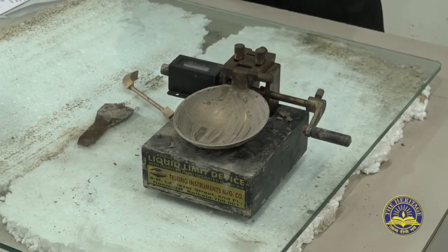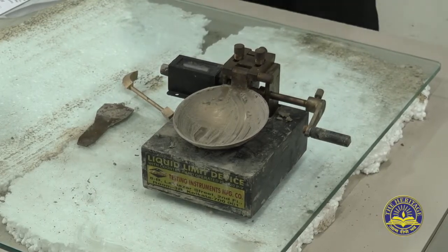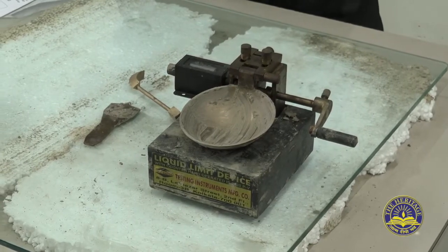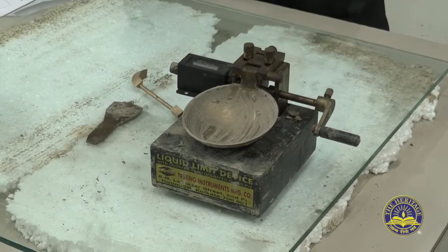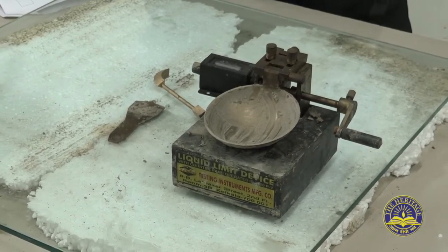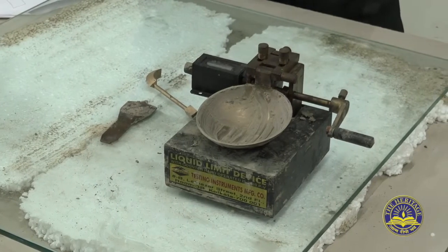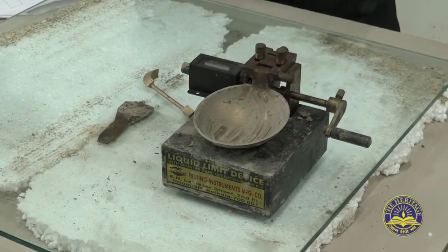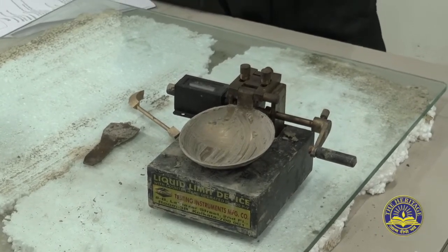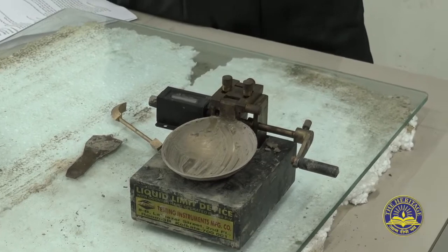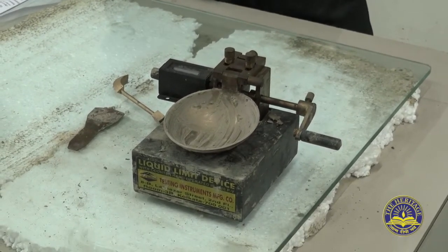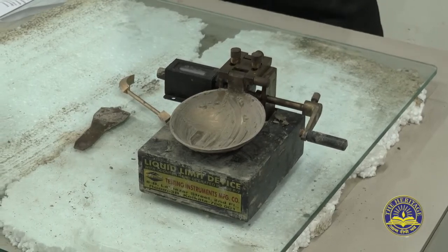And after doing all these things, you have to do a graph plotting, that is number of blows versus moisture content. Number of blows will be in the logarithmic scale, moisture content will be in the ordinary scale. After plotting those 5 or 6 points, you will get a straight line. And corresponding to 25 number of blows, that is the liquid limit. From the graph you can obtain that. So this is liquid limit test.